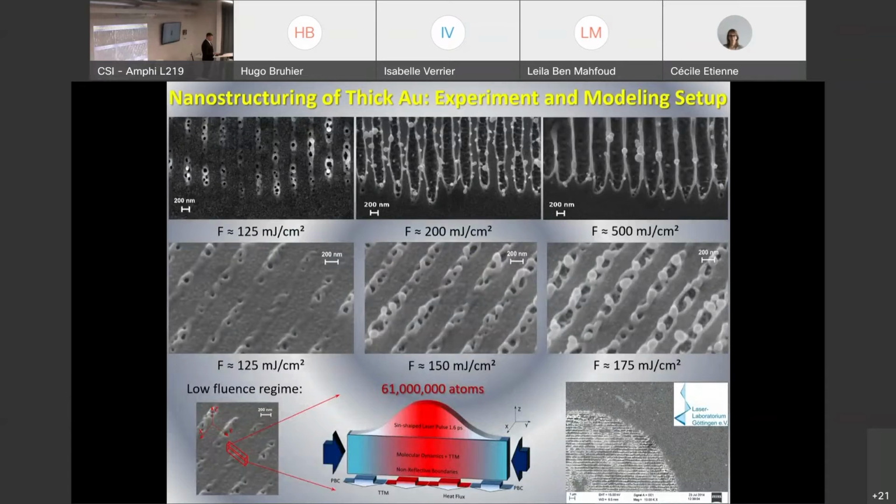So for that purpose, we also identify the geometry of the experiment. First we utilize periodicity in one of the directions. Then we also understand there are no temperature or pressure gradients here, so we can also apply periodic boundaries here. We resolved atomistically only the pre-surface region of the material, where the most intensive processes, including phase transitions, can happen. So at a certain depth, which was here about 200 nanometers, below this depth there are no phase transition processes, therefore it's not necessary to resolve it with expensive numerical molecular dynamics calculations.